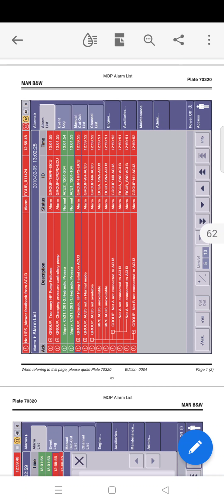Now the alarm list. So what do we get from the alarm list? The alarm list contains the central facility of the alarm handling, allowing for display, acknowledgement and cutout of raised alarms. So what we can do from this screen: we can acknowledge the alarm, we can cut out the raised alarm, and a detailed explanation can also be accessed from this screen. The alarms can be grouped to simplify the overview of the alarm list and are displayed in chronological order with the latest alarm on the top.